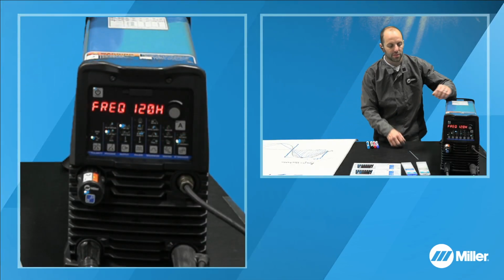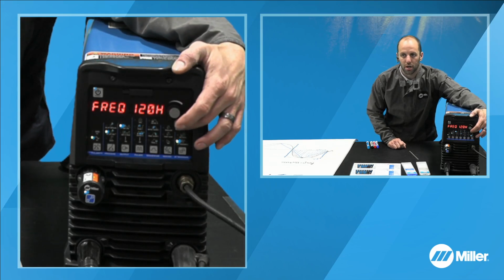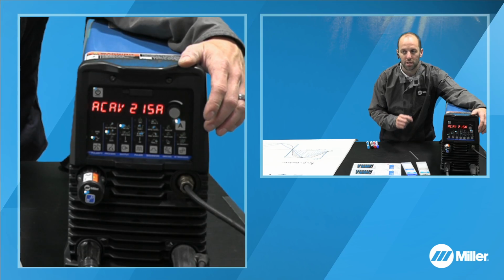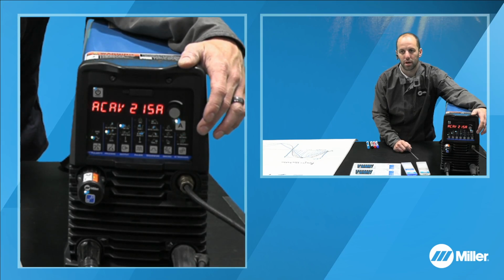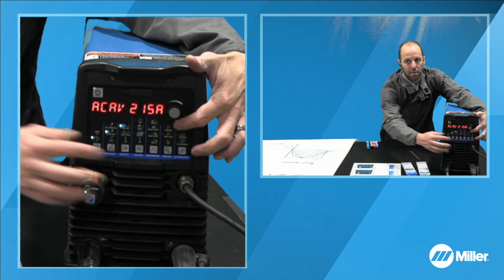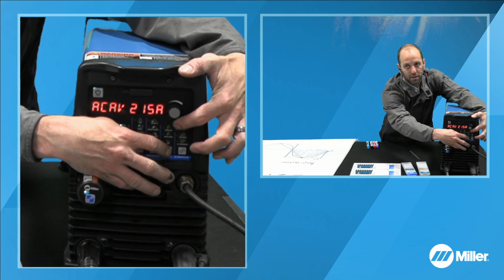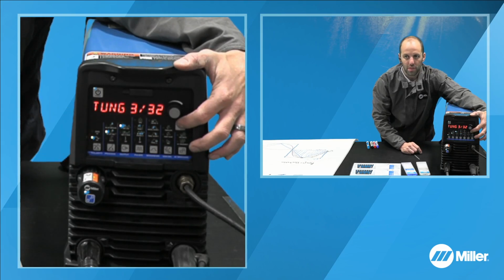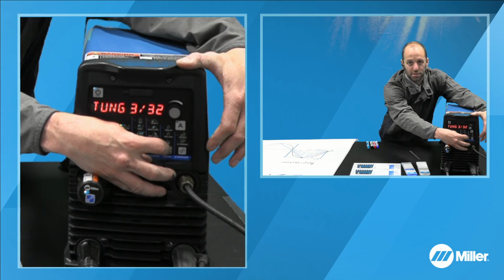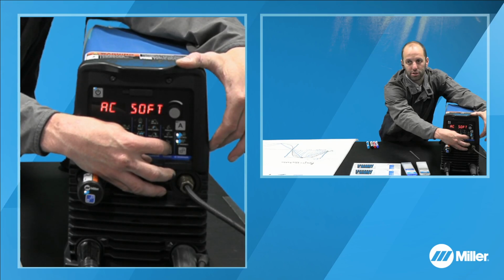So when we look at the actual front of the power source, in order to get into the different waveforms, similar to when we were getting into the tungsten sizes, we're going to use the A button or the amperage, and then our gas dig button here. So you see here, again, tungsten size is the first thing that pops up. We're going to use the amperage button, or the gas dig button, sorry, in order to scroll through here.